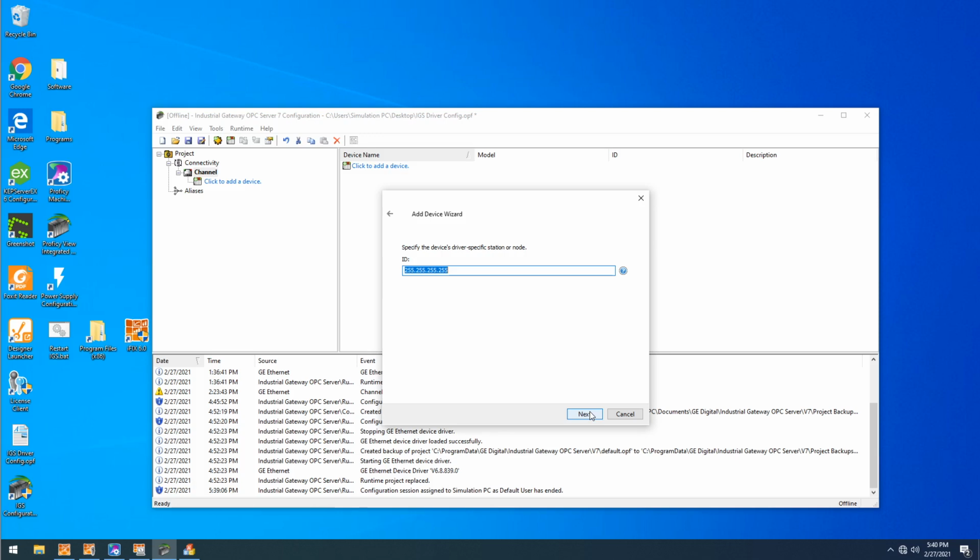Instead, this is going to be the IP address we've actually statically defined for the network module, so that IC695 ETM001 card occupying slot 4 in our rack. And that is 192.168.1.100. Now, this host machine is on the same subnet, so the IP address of this host machine is actually 192.168.1.200. So it's important to make sure that you can communicate with, in this case, your ETM001 card, because I'm on the same subnet. So just make sure you can communicate.